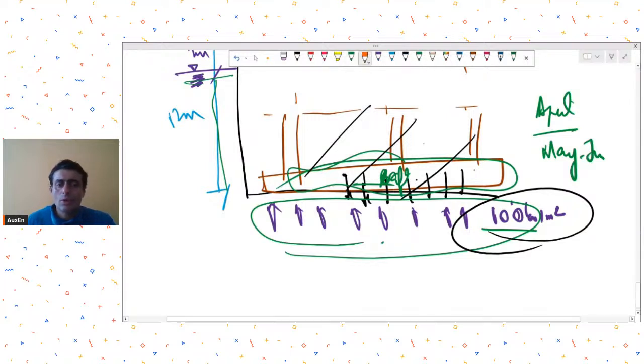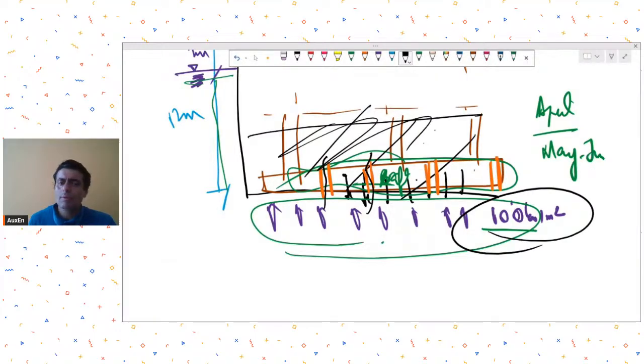Number one, you try and release this pressure. How to release this pressure? You may leave vertical gaps or holes. We have done this kind of work in our projects where we have just left holes in the raft, so that even if rain occurs, the water will just come in and fill up your raft. No problem. The raft will get flooded. Absolutely no problem. Let the raft be flooded.